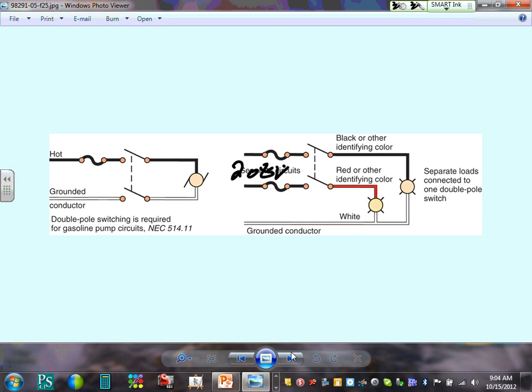You are looking at it right there. Two-pole snap switch. Not commonly used. Right? So you need a switch that looks like this. So be very careful when you align your switches with your circuits. The best practice is every circuit, assign one switch or more than one switch for every circuit. If you put two circuits in one switch, you are dealing with two pole.